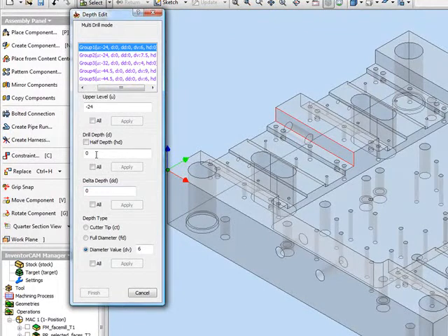I've edited them all to the depth to be at 0 height for that particular hole. And in each group, I've told it that I want the 0 depth to go down to that particular hole's diameter. In other words, only 6 millimeters of the diameter of the tool will get to that 0 depth. And I've done it for every single group.